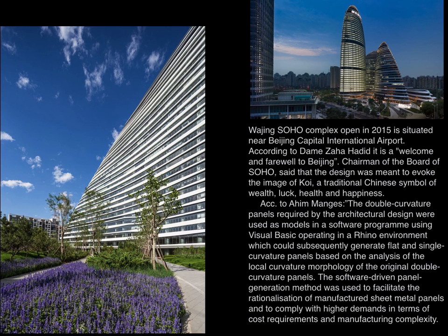The double curvature panels required by the architectural design were used as models in a software program using Visual Basic operating in the Rhino environment, which could subsequently generate flat and single curved panels on an analysis of the local curvature morphology of the original double curved panels.